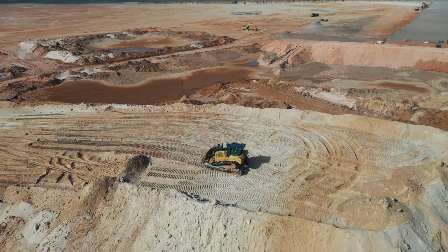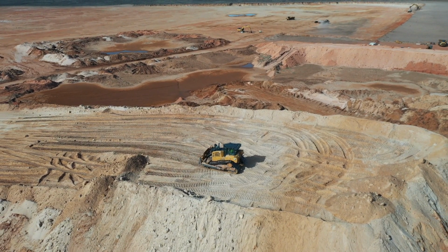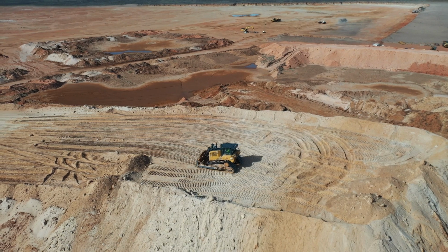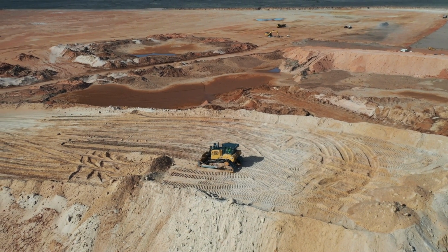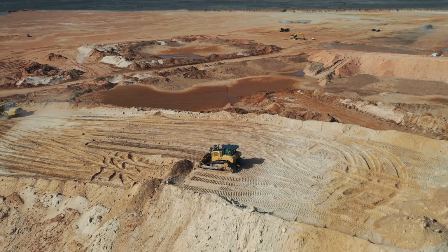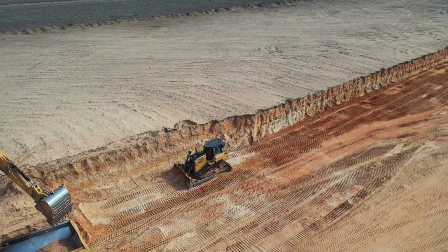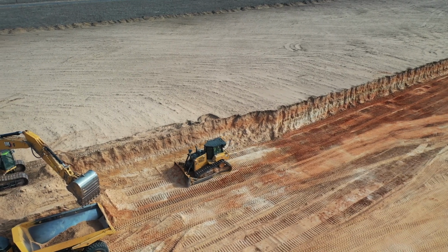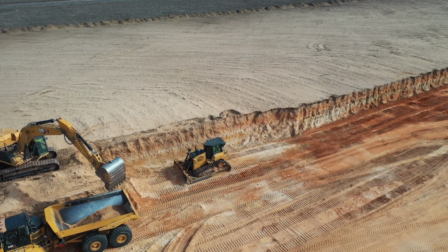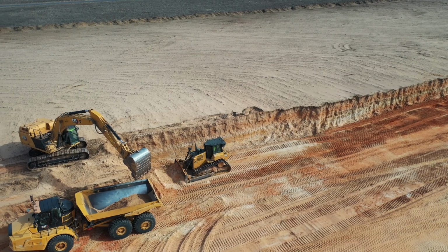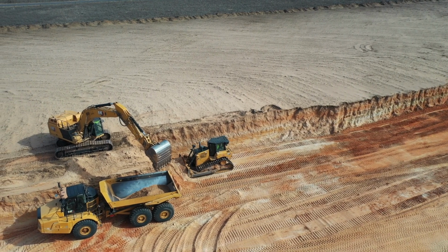Keep work areas as smooth as possible. This results in easier maneuvering and minimizes operator fatigue. To maintain a smooth surface, make a small cut carrying material in front of the blade. When dozing to an excavator or loader, make sure you and the excavator or loader work together to avoid equipment damage or personnel injuries.